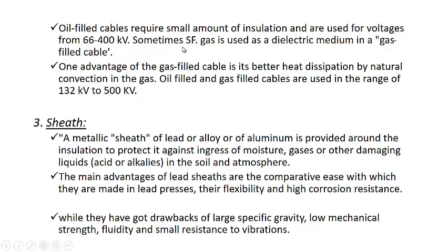Sometimes SF6 gas is used as a dielectric medium in a gas-filled cable, because SF6 has good insulating properties. One advantage of the gas-filled cable is better heat dissipation by natural convection in the gas. Oil-filled and gas-filled cables are used in this voltage range. Oil-filled and gas-filled cables are slightly difficult to construct.